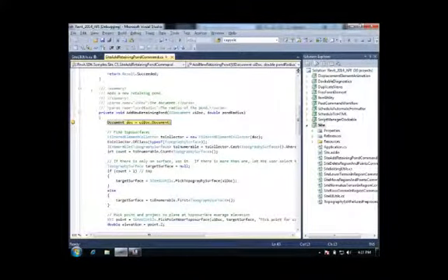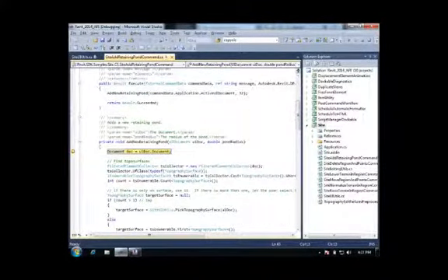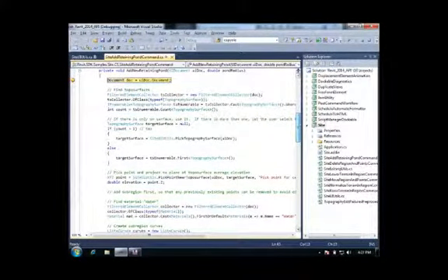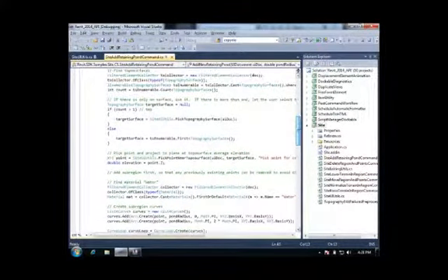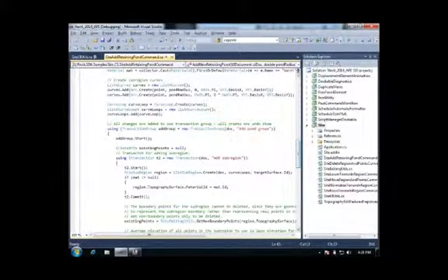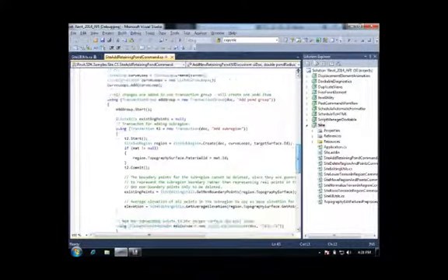I've set a breakpoint here in the add new retaining pond method, which shows you the steps that we go through. We either pick a topography surface or we select the first one found in the document. We pick a point on the surface to define the location of the pond. We create the curves, in this case 2 arcs to define a circle.